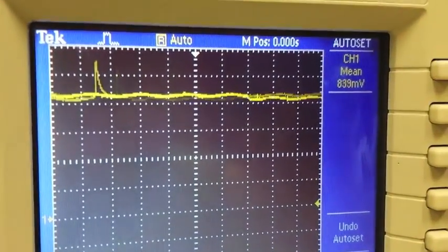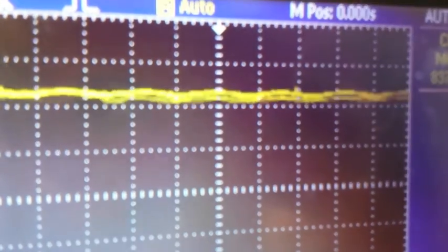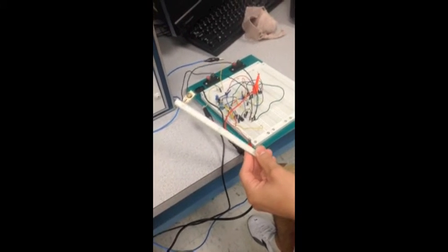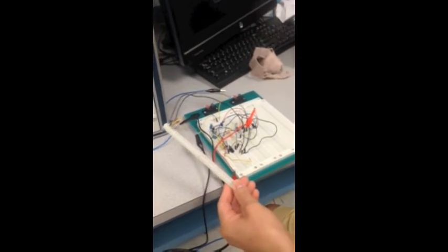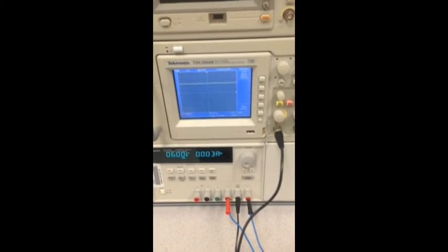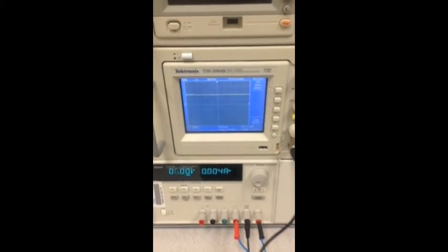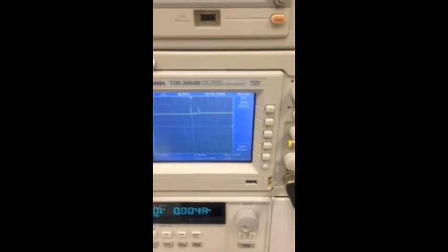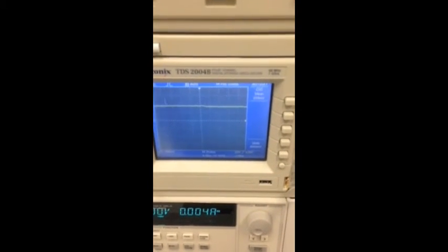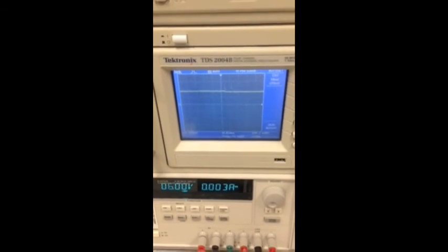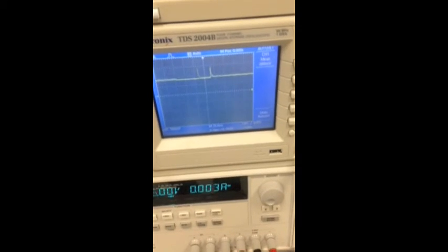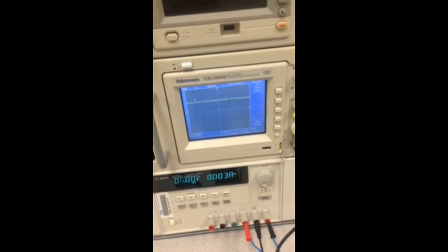The second amplifier has a low-pass response, and it sums the output of the first amplifier stage with a DC offset voltage from a potentiometer. Then it will be adjusted to optimize the DC level of the signal to the LM3914 and zero the display. Then the envelope detector processes the signal to condition it for the display, with a switch to select between the two modes of display. And finally, the piezoelectric vibration sensor will be the interface between the subject and the transducer.